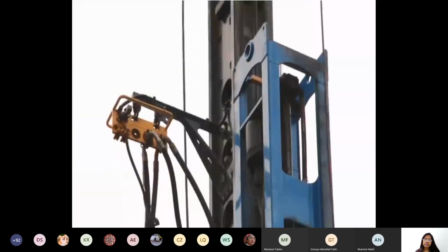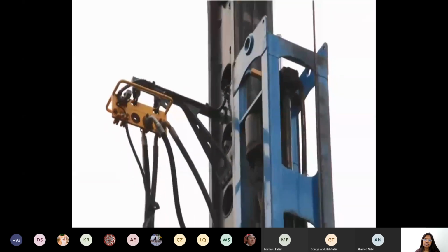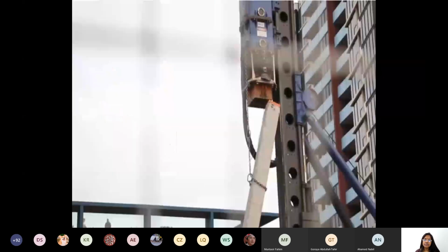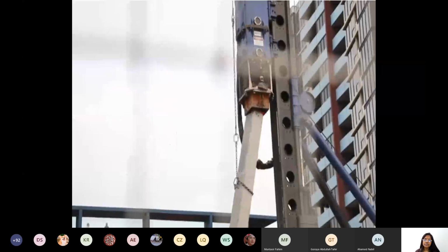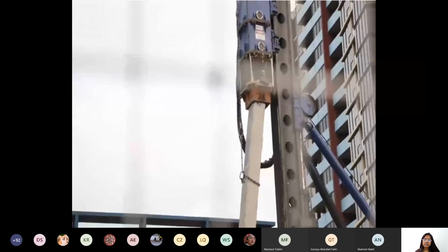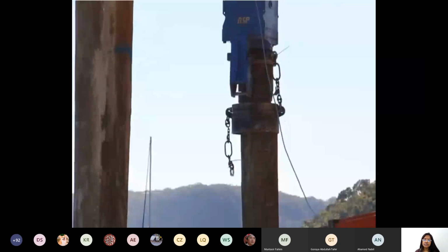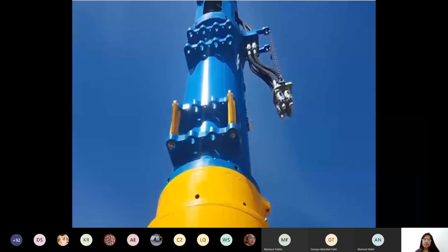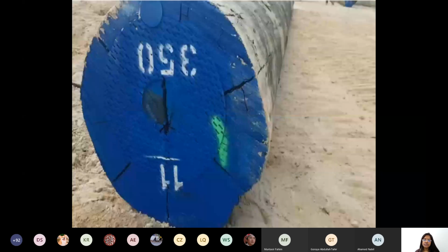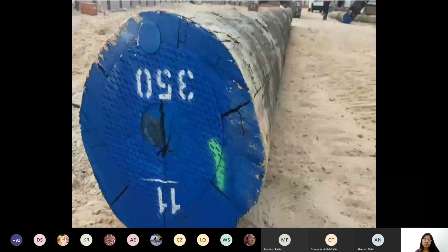The impact hammers used on the rig are the main assembly performing all the work and should be carefully considered, depending on the work required. Impact hammers can vary from 6 tons weight to approximately 40 tons weight, obviously depending on the diameter, length, and ground conditions.